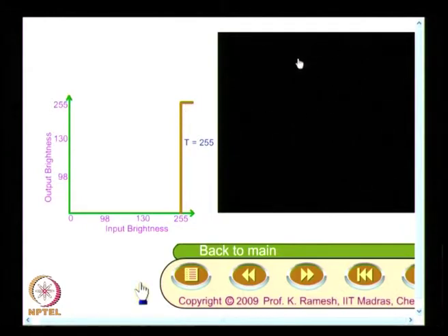That is why you see this as a black picture, because the image has 0 as pitch black and 255 as white. If I make all the pixels black, I will not see the picture at all. But because photoelastic images have high contrast, you can apply a very simple image processing approach called thresholding to identify fringe areas.